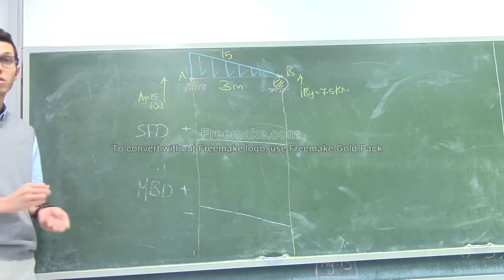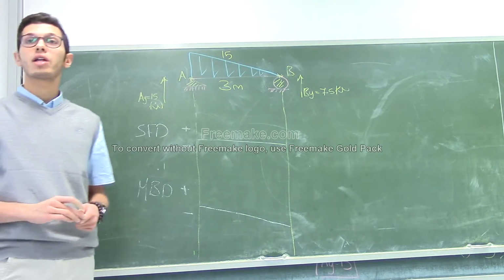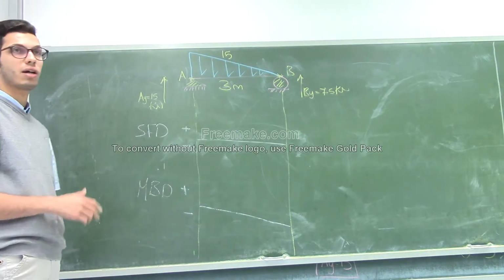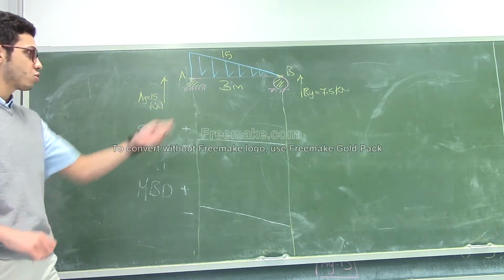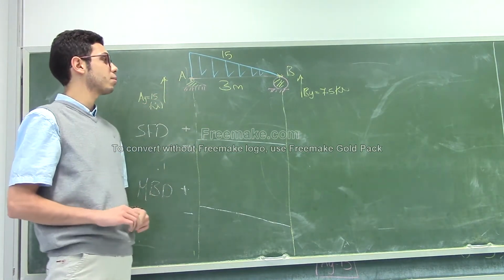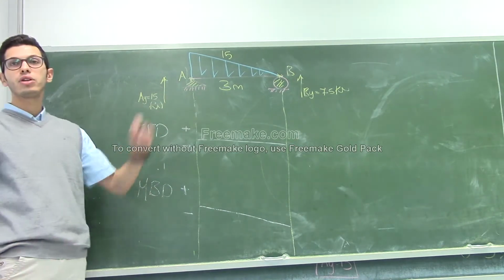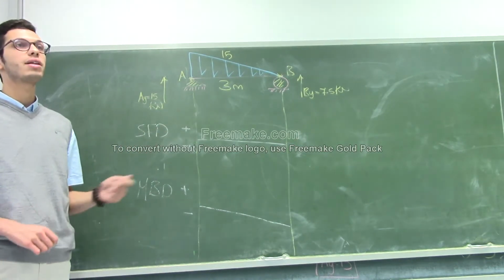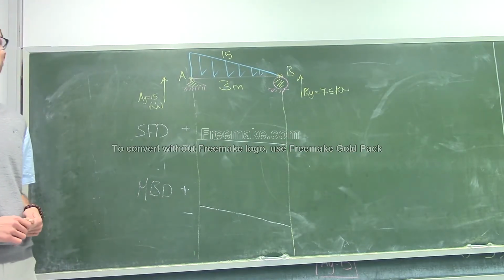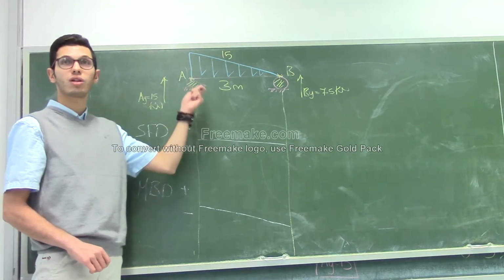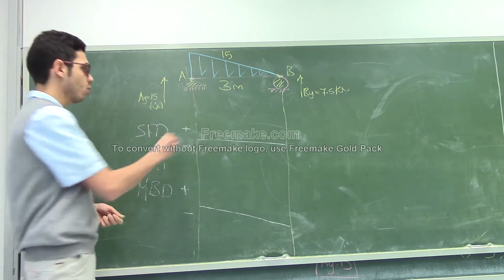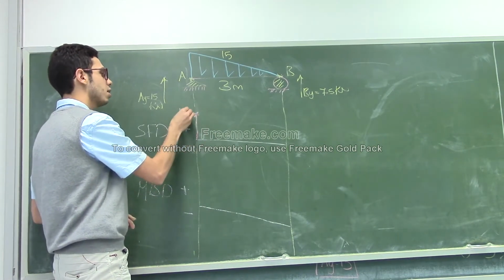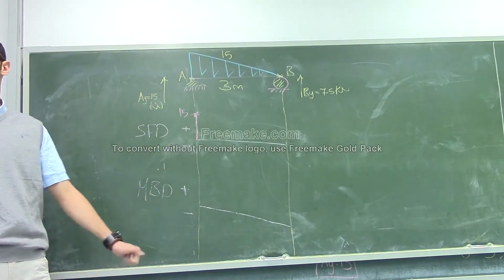Let's start over, starting from point A. Please all of you focus with me, I will give you time to write, because this is one of the most important exams. Now at point A, we have a reaction equal to 15 kilonewton, right? And it's upward. That means on the shear diagram, I should go upward 15 points, right? So I will go upward here, 15 points, like this.